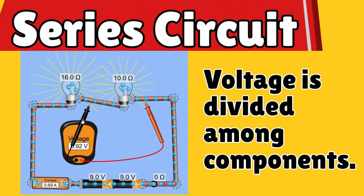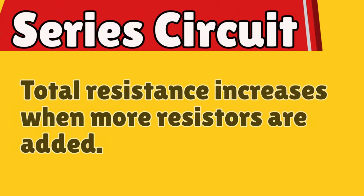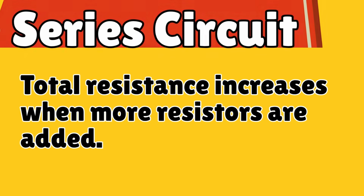Sometimes it measures 18 volts and sometimes it measures 11.08 volts and sometimes it measures 18 volts, while the current, 0.69, does not change. So the current remains the same. It flows through all components. And the total resistance increases when more resistors are added. And that's the reason why it is dimmer when we use two bulbs in the first circuit.